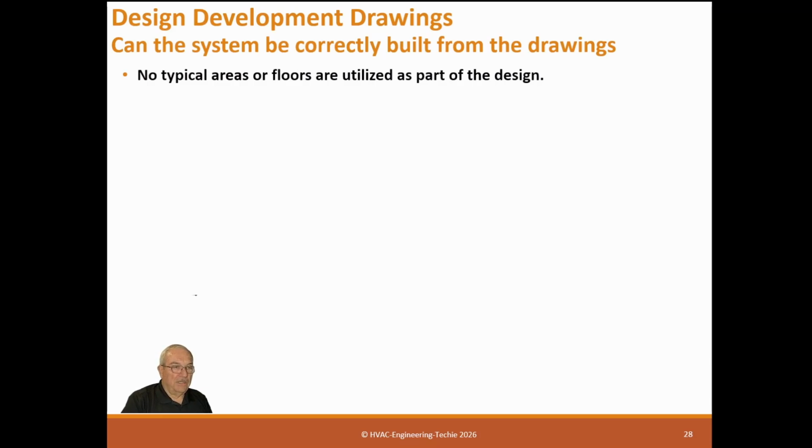You can't keep track of what you're doing. You have to have unique numbers, and you don't have drawings to support it. You should never do it. Even if the floors look exactly alike, they're not. The rooms aren't going to be numbered the same. So you need to show every floor of the job. It makes it impossible to build otherwise.